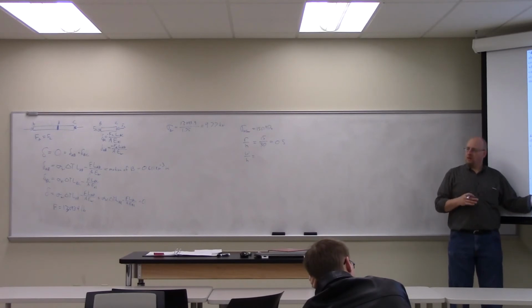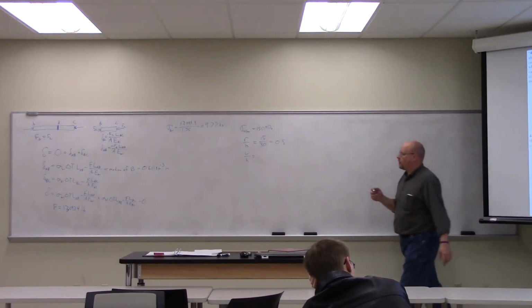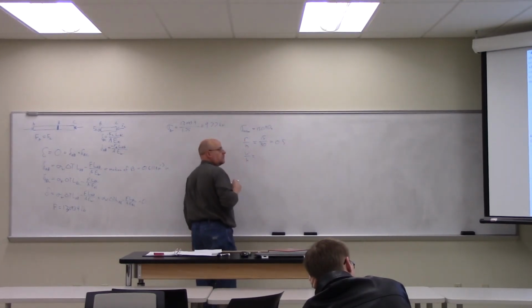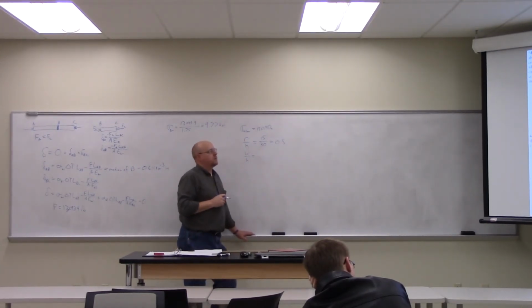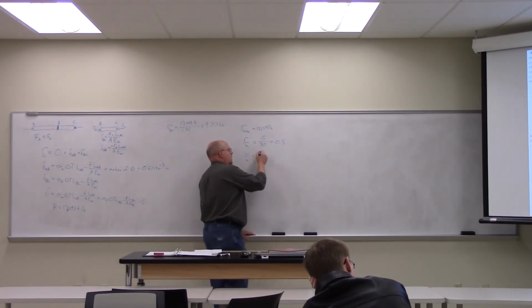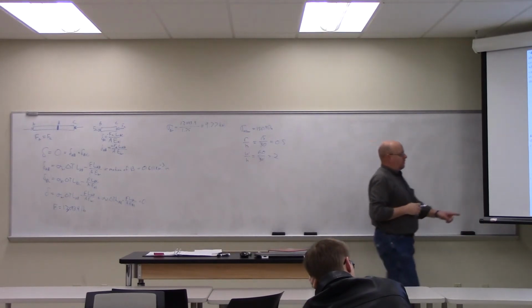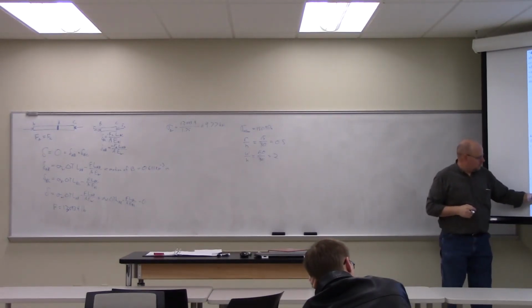All right. So I got a whole bunch of little blue lines on here. How do I differentiate which blue line I'm supposed to use? W over H. Right. So what's W over H? W is the width of the thick section, 60. And H we already know is 30. So that's 2. So now I find my W over H equals 2 line, which is this one.